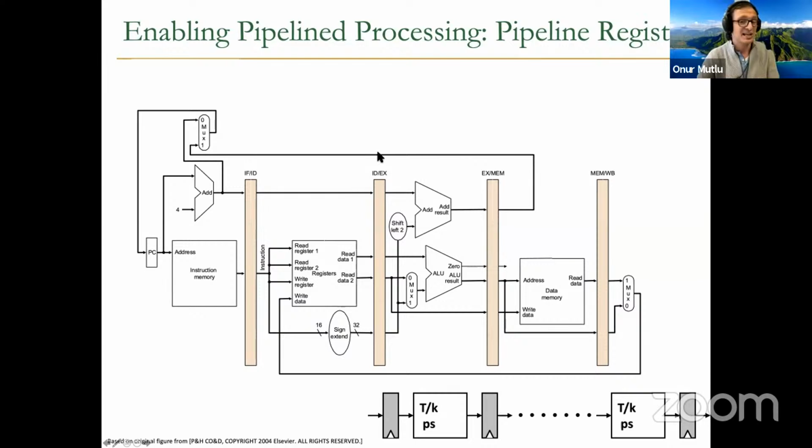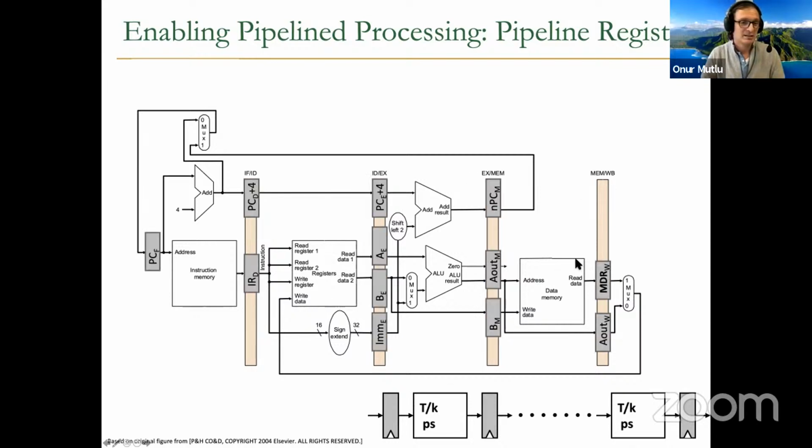Instruction fetch / instruction decode, instruction decode / execute, execute / memory, memory / write back. So we need to have 4 pipeline registers, as you can see over here. Meaning that at the end of the stage, all of the results that you need later on should be latched into the registers. True for this stage, true for this stage, true for this stage, etc.